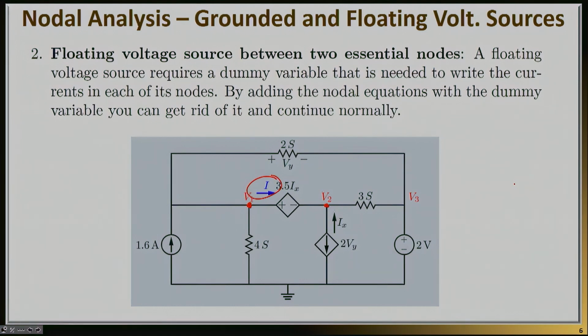Now, there are other methodologies you can equally well deal with this. For example, in other textbooks, there is the concept of a supernode, which essentially does the same thing with a fancier name. In other textbooks, you will also find something called modified nodal analysis, a technique specifically made to deal with floating voltage sources, and essentially does exactly what we did right here. But I really don't think you need this type of fancy names. All you need is a clear mind and a logical approach to things, and you can very quickly get the solution as we're discussing here.